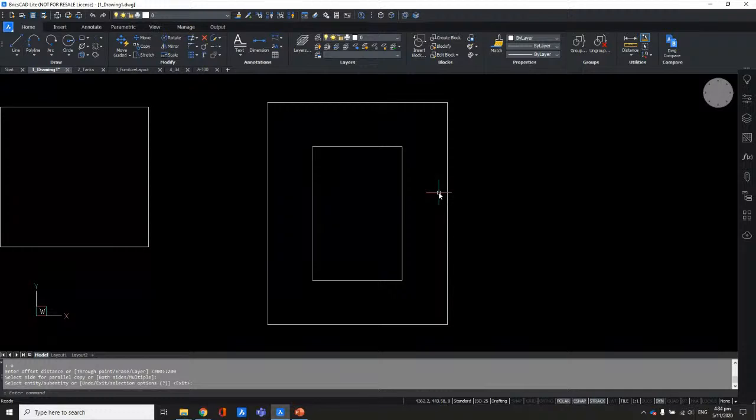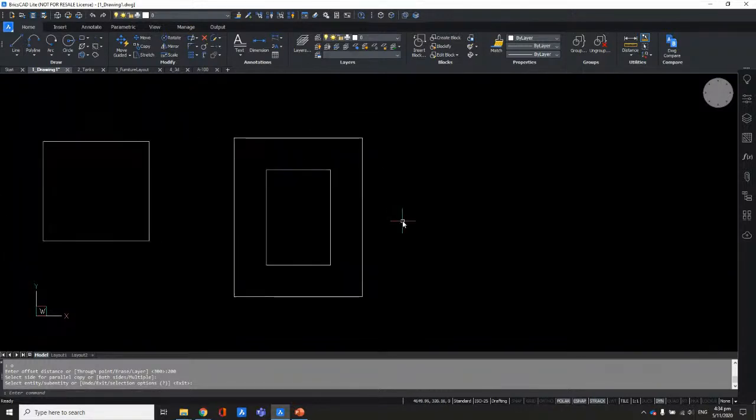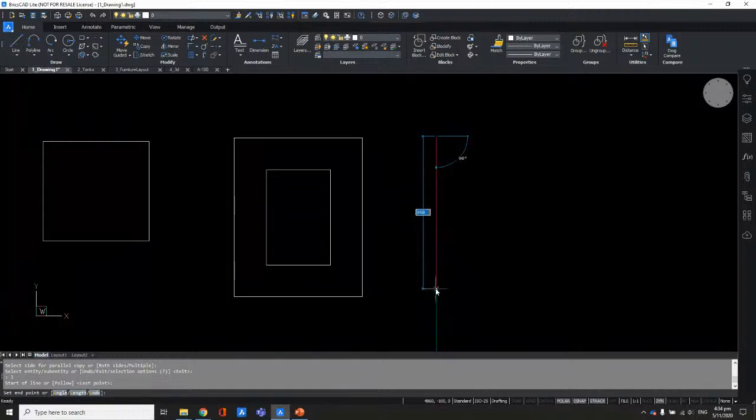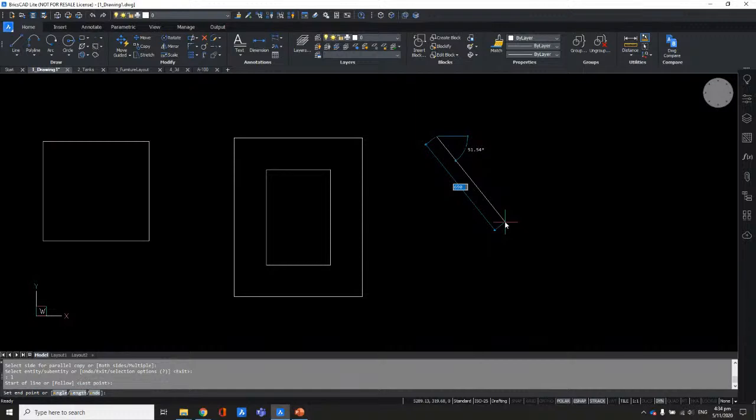And then further to the dynamic dimensions that we mentioned earlier, you can also see that if I am drawing a line, that dimension is also shown to me. And since I don't have my ortho on, when I do any angling, you would see the angle is also shown. So this angle, let's say I wanted this line to be 1000, but I want the angle to be, let's displace it at 1000, and then the angle I want it to be 60.